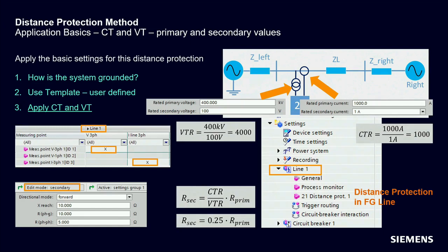But roughly speaking, it is important for the distance protection to have the proper CT-VT settings and also to know what impact they can have on the distance protection mechanism operation. So here are some screenshots, very busy slide. Don't like those normally, but let's have a look.